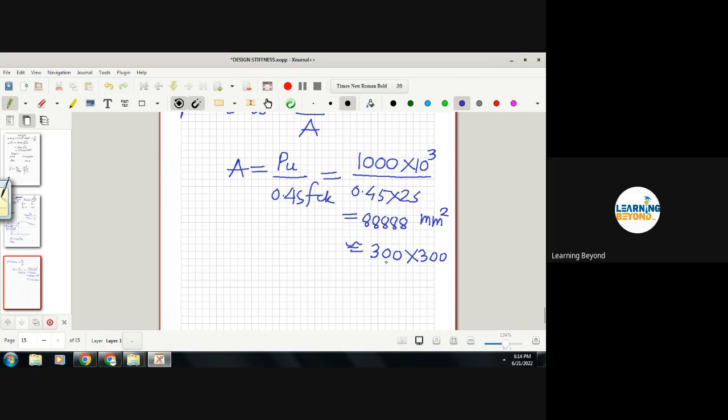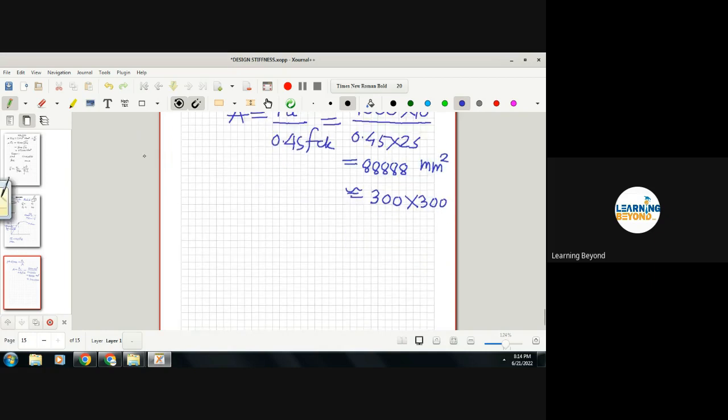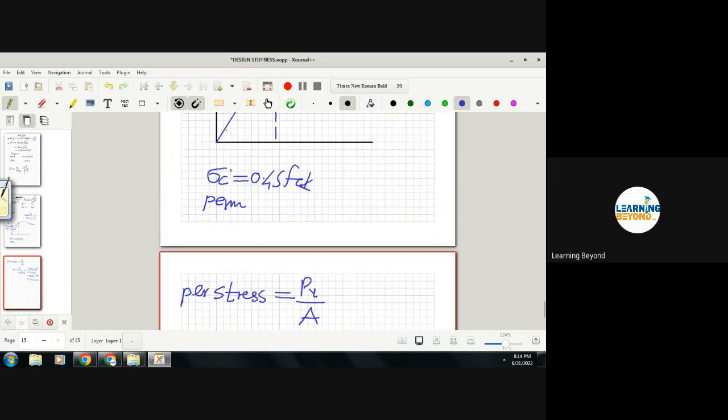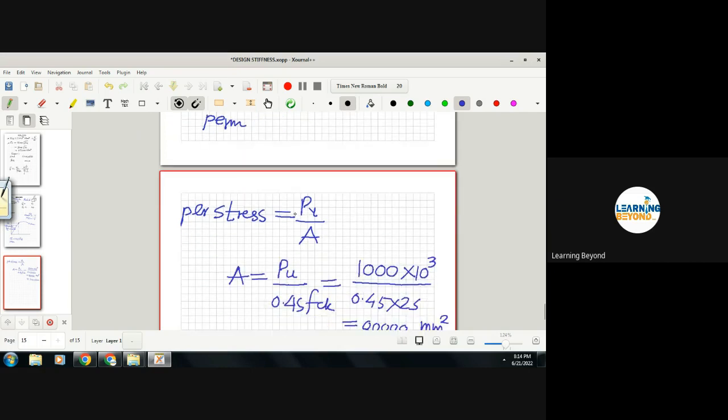It is the same as we can say for steel also. So you can understand from these examples that whatever material you are using, first of all you should know its stress and strain graph. Then you should know the yield stress. Then you should know the factor of safety to be considered for that material. Factor of safety for different materials is different. Once you know the factor of safety, you calculate the permissible stresses, and once you know the permissible stresses, you can design any section for that material.